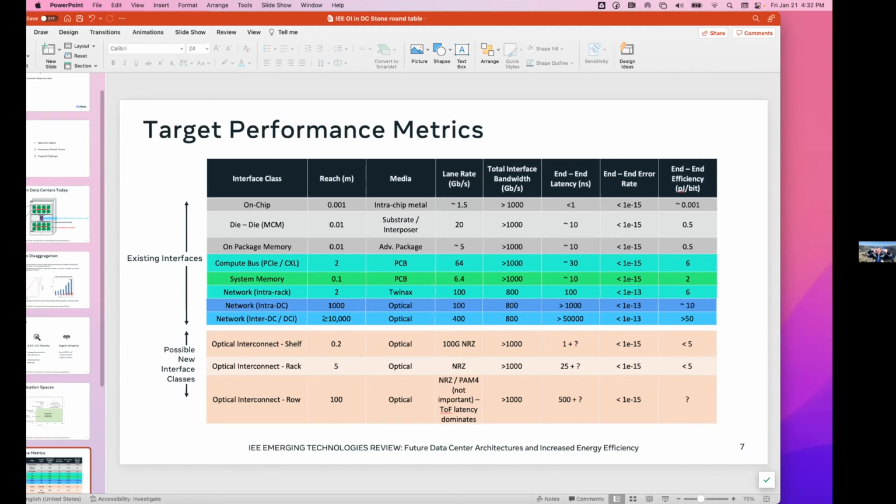So you could look at the die photo and maybe get an idea. At one end there were two big dies on there. Each one of them exposed 2 edges covered with HBM and 2 other edges, and you can imagine the 2 other edges is where the 64 lanes of SerDes live. I don't know if there's enough detail in those die photos to figure out exactly where the SerDes are and how much of that is SerDes, but I don't have that right offhand. Rob, it would be a methodology to get to that shoreline density. And HBM also has a well-known shoreline density in the industry.